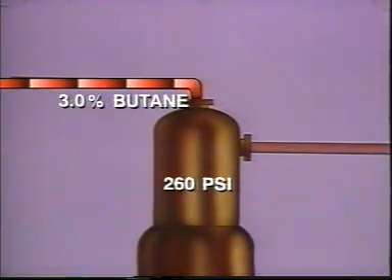Consider what happens in the tower that is separating butane and propane when the pressure is reduced. The lower pressure allows more vaporization to take place, which increases the amount of butane driven overhead. The overhead product gets heavier and more of it is produced. So when we reduce the operating pressure, we get the same effect as we did by reducing reflux or increasing reboiler temperature.